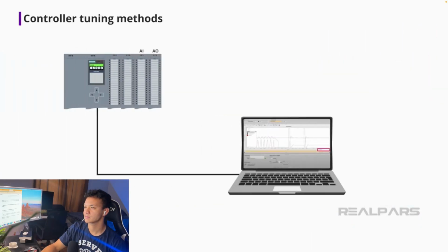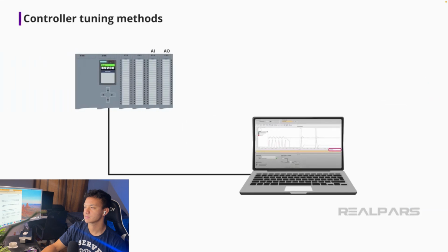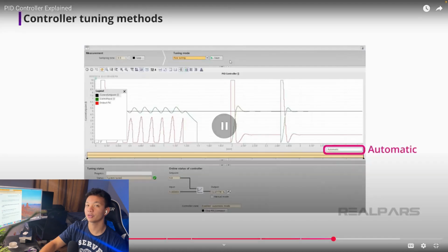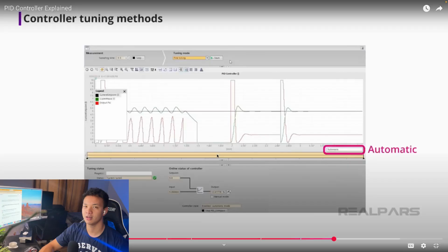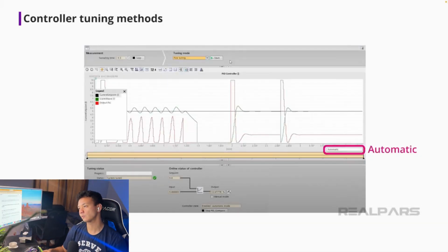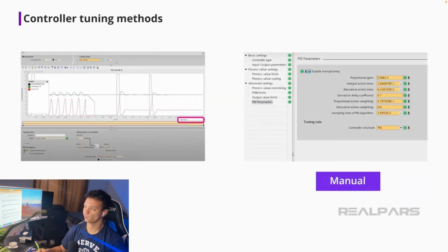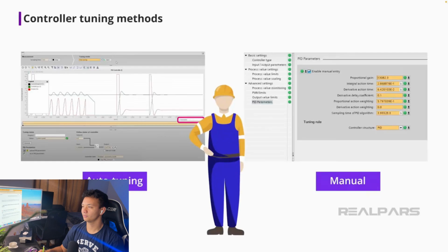Most process controllers, PLC, and DCS loop controllers sold today have auto-tuning capability. Auto-tune? Oh wait, say less. The PID controller learns how the process responds to a change in set point and suggests PID settings, regardless of whether the initial PID parameters are derived from the manual or auto-tuning methods. Additional tweaking is often required by seasoned automation professionals to get the response desired.